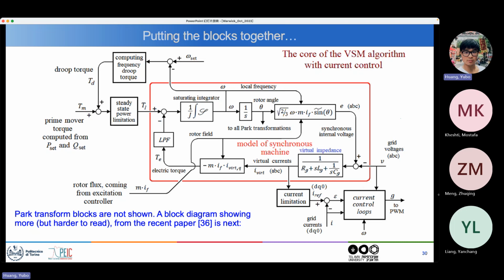So that means if they want to oscillate against each other, then this oscillation will dissipate energy, so it will damp the oscillation. Yes, and you can introduce this virtual friction between generators in a grid, and it has a very nice effect of killing the inter-area oscillation between generators. And what you need to be able to do this is communication lines between the generators.